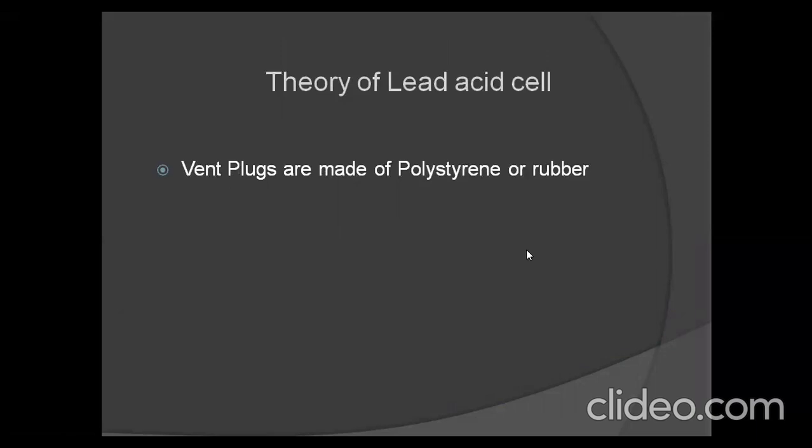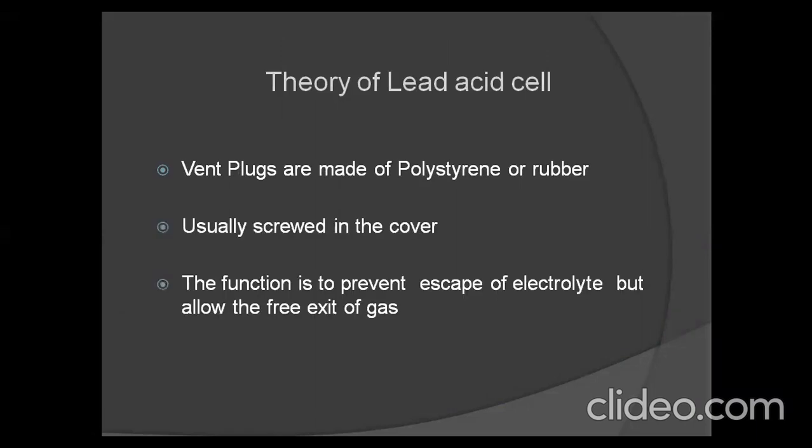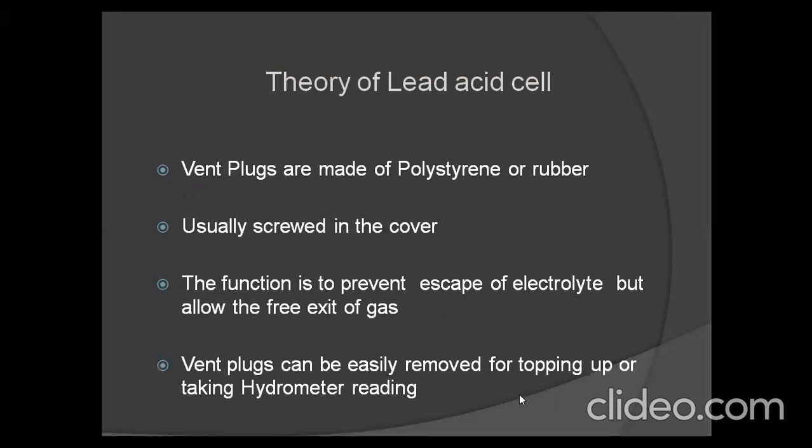Vent plugs are made of polystyrene or rubber, usually screwed in the cover. The function is to prevent escape of electrolyte but allow the free exit of gas. Vent plugs can be easily removed for topping up or taking hydrometer reading.